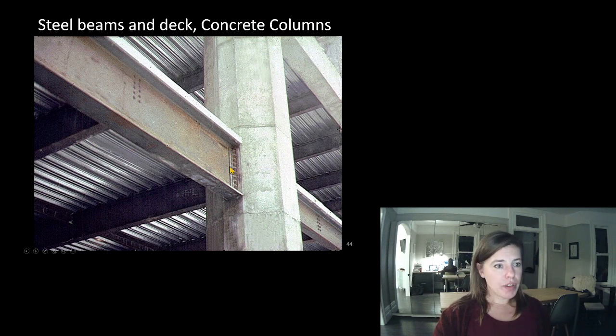This is a crazy weird construction. We don't tend to add steel to concrete unless it's a retrofit. So you can see that there are concrete beams up here. So it looks like there are things in this building that were concrete to concrete. I have done projects where there were concrete buildings that they needed to add a mezzanine, for example. And so for those, we added steel into it. So this wouldn't be based on preliminary construction. This would usually be an add-on.